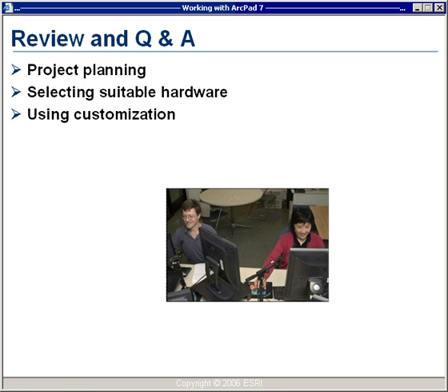The second type of differential correction is termed post-processing, and this type of differential correction is always done back in the office once you've brought your data from the field onto your desktop PC, and then use desktop tools to perform post-processed differential correction.